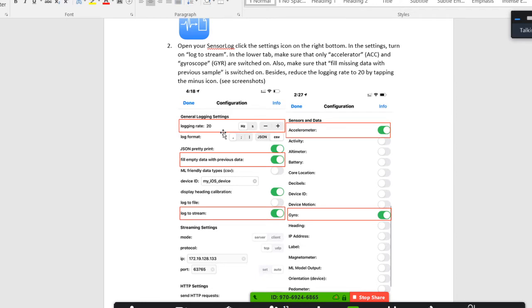So this is called Shannon sampling theory, or the Nyquist sampling theorem. Your sampling rate should be at least 2 times faster than the highest frequency you want to measure. So for example, when we do exercise, I can never reach 10 hertz.